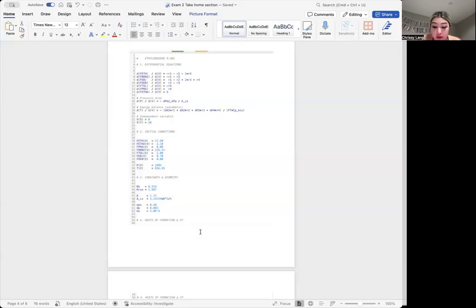Second, my implementation for the reversible reaction may not match Aspen's exact equilibrium constants or activity conventions, which can shift the distribution between ethylbenzene and heavier byproducts. Aspen can also include phase equilibria, whereas my model treated the system as a single gas phase with no condensation, which affects both composition and heat capacities.